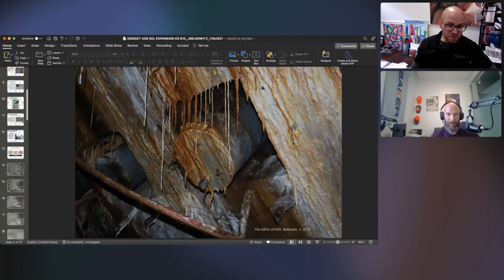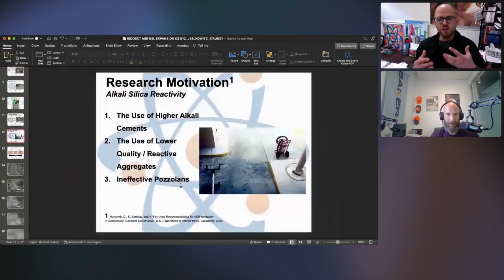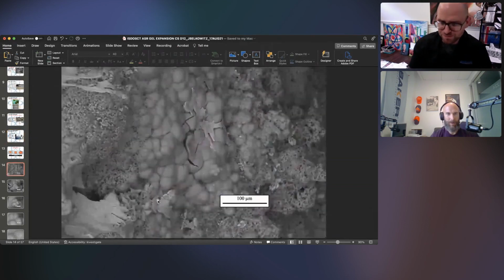But when we look at it under the microscope, here, it is in Denver, Colorado, right? Where it's been exacerbated by the de-icing salts and brines and the wetting and drying cycles. When you see ASR damage, it has a very significant look to it. Primarily it's these Isle of Man cracks that are 120 degrees apart. They look like the flag from the Isle of Man. That's why we call them Isle of Man cracks. And they have these salts and gels coming out of them. But when we put it under the microscope, it really is one of the most beautiful things in the world.